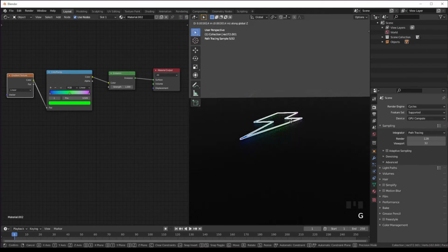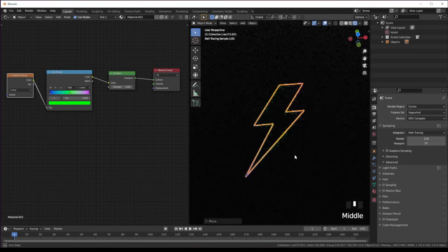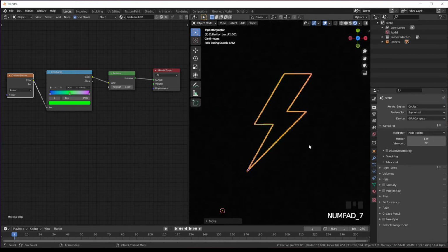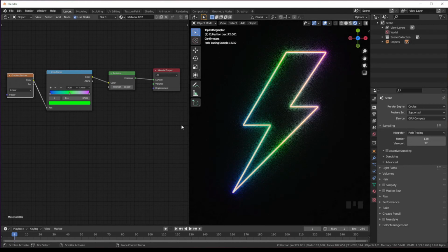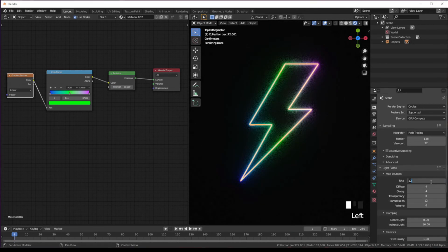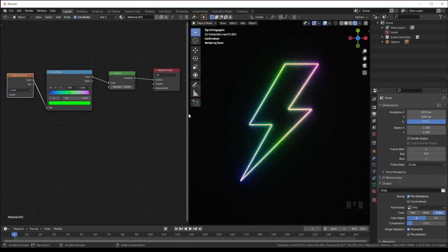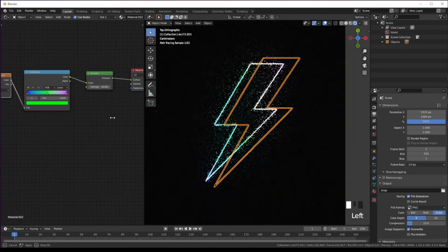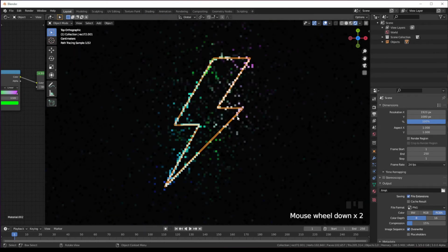Now we can play with the emission strength and the distance between the logo and the background plane as we want, until we are satisfied with the result. Remember to check the render settings. With low samples you will not get good results, as we are working with a very sensitive amount of reflecting light. I used in my case 1024 samples in the final render. You can play around with the values until you are satisfied.